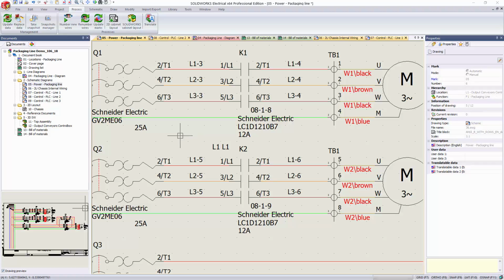Some companies have standards that may still make this undesirable, such as if you number all of your components based on the page that they're on, you wouldn't want to change your page numbers all the time, especially if you have already built the system and you've got labels on all your components in your panel. You don't want to have someone have to reprint those labels and go update them all the time.